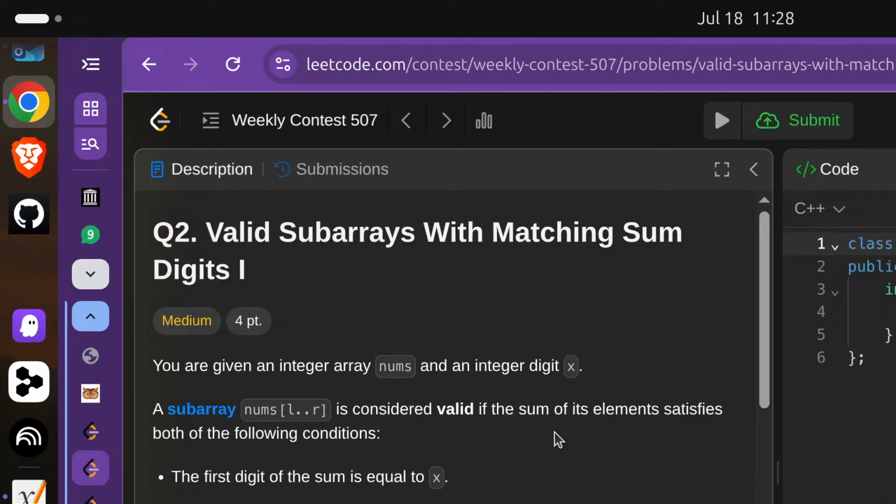When Vikram 1 ascends into the Earth's atmosphere, its nose tip can face around 15 watt per centimeter square of heat flux. That's pretty large, I mean, as compared to humans. Yeah. That's right. And we really need to design a thermal protection system to keep the structural design under the set constraints. If we don't design any thermal protection system, the vehicle surface might end up going to 1500 degrees Celsius, and